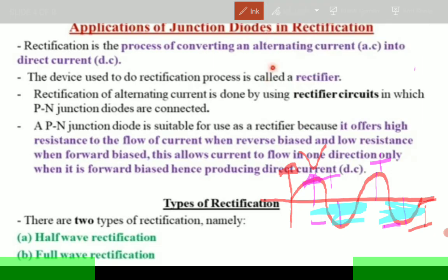Direct current is going to present a waveform of this nature, like this. The lower part, which is the negative part, has been cut off, removed by the action of the diode conducting, because of its tendency to conduct current in one direction. So the diode cuts off or removes the bottom part, which is this part here. That's what a diode can do. The lower part is removed, so that only the positive part remains.